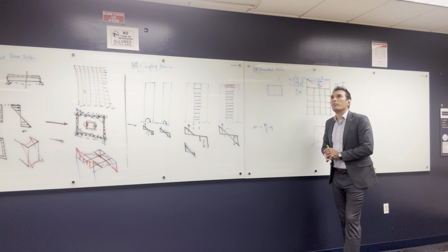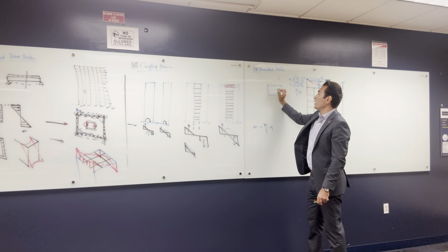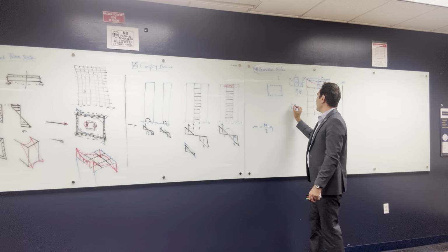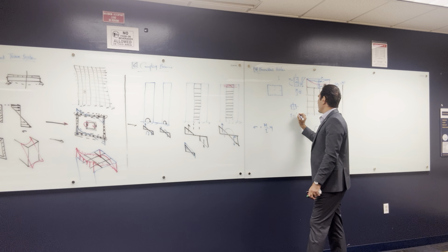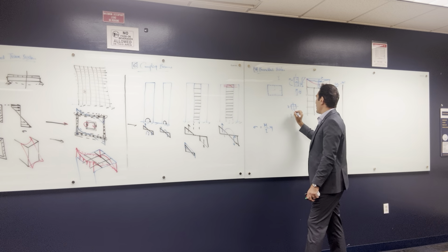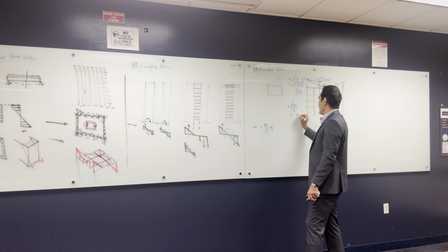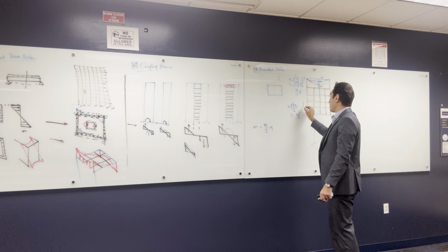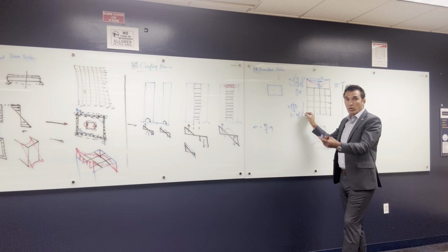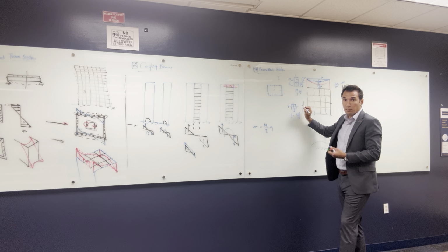If you remember, you take this in dynamics and structural engineering. If you wanted the inertia of a column, let's say it has A and B, and you want to find the inertia about this axis, it's going to be B A cubed over 12, right? And this is about this axis. But if you want to find it about an axis that is translated from here, the inertia is going to be bigger or less? Bigger, right?